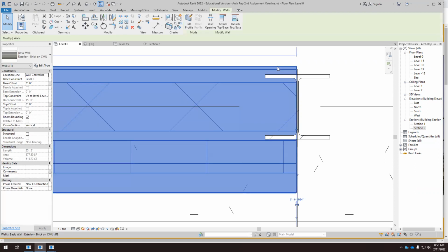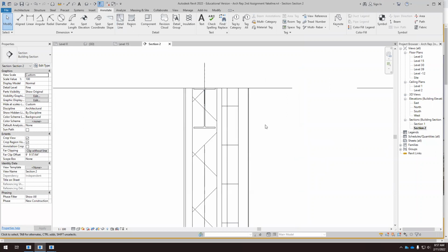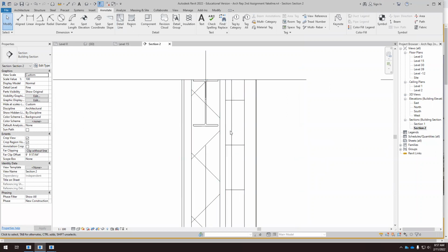This is the solid element, this is the gypsum board, so I can't interrupt the gypsum board because I have a column. But I can have this column within some air cavity. So this column is within this air cavity, and there it's within the other air cavity. So that's acceptable. And if we look at the section, it's not affected because I have the air cavity here, and another air cavity there, and that's fine.